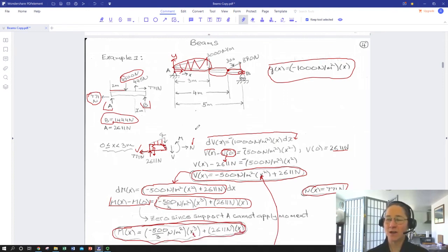And at that point, you're going to be leveraging your differential integral expressions, Q, V, and M. Basically, integrate to get upwards from Q to M, take derivatives to get from M to Q, and the trick is always, always, always the limits of integration.